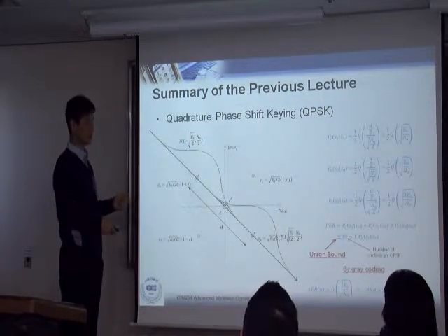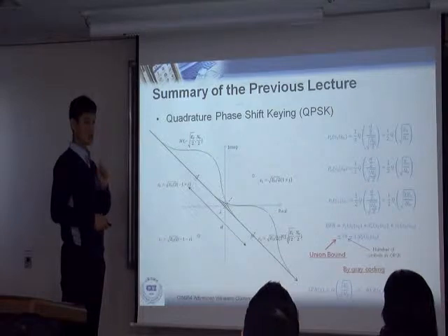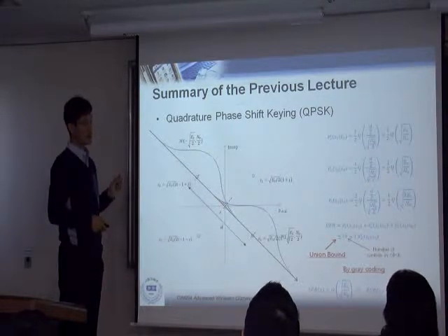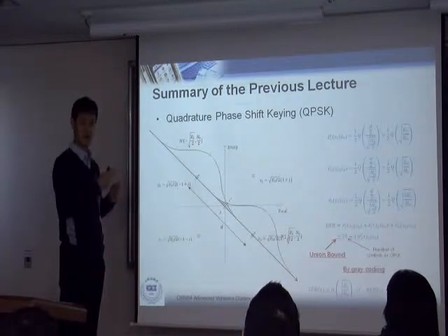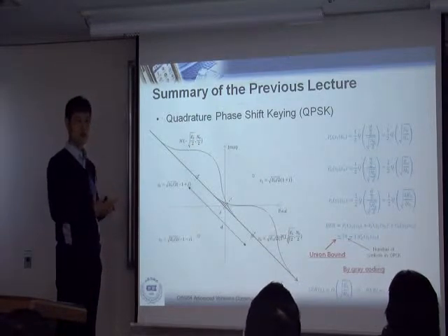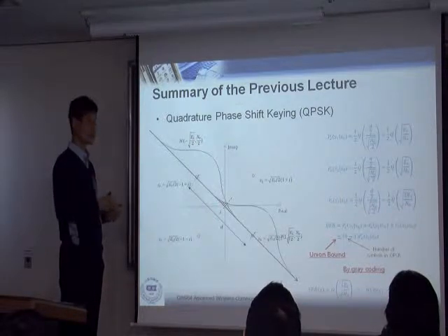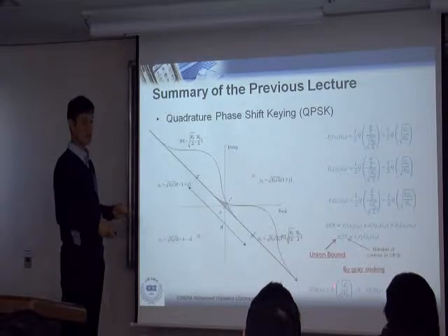These 2 are the same because one symbol is 1 bit for BPSK. But in QPSK, one symbol has 2 bits in it, so BER and SER are different. You need to understand this clearly. A lot of people confuse them and sometimes use them interchangeably, which is very wrong.